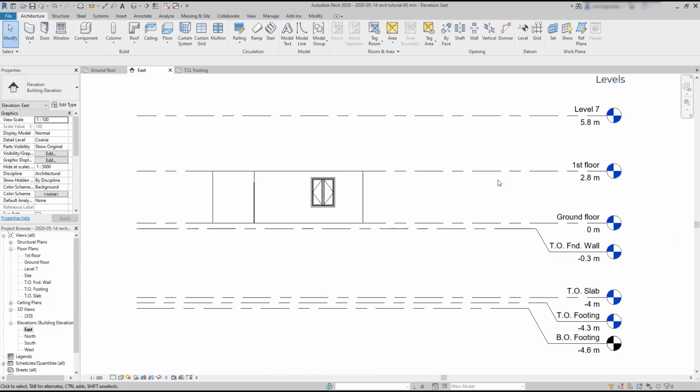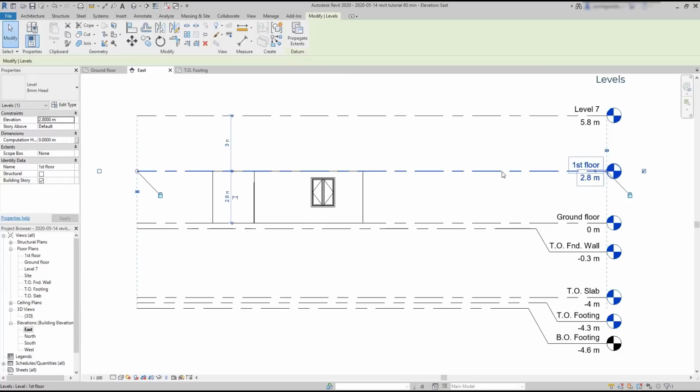To modify the level heights, I already showed you. It works the same way as for other elements like walls. Click on the one you want to move, and then change the lengths of the temporary dimension lines that appear.